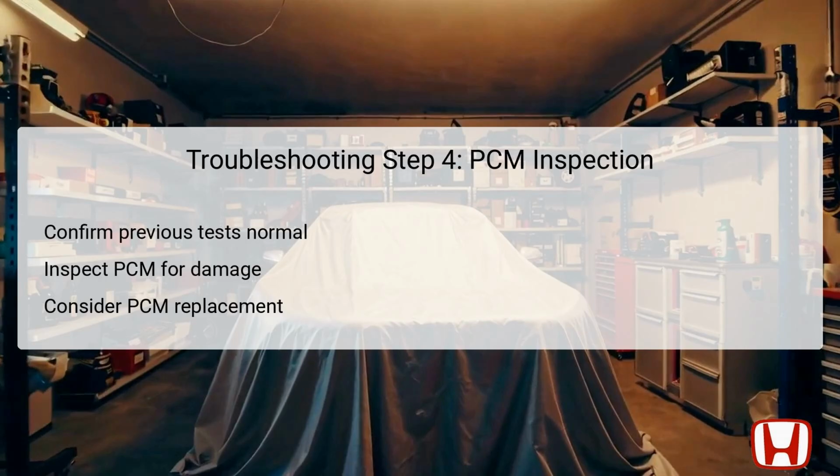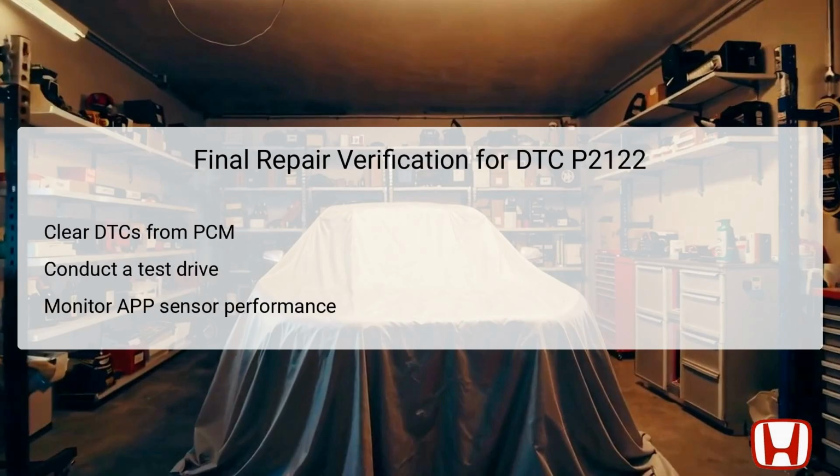optimal vehicle performance. After addressing the issues associated with DTC P2122, it is essential to conduct a final verification of repairs. Start by clearing any stored trouble codes from the powertrain control module, PCM, using a Honda Diagnostic System, HDS. Once the codes are cleared, perform a test drive to evaluate the vehicle's performance and responsiveness.